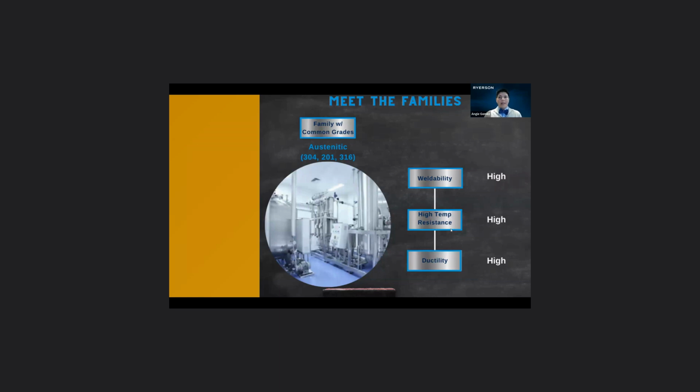If you see an L, for example, 304L on a test report or stenciled on any material you might have received, that means it has a low carbon content, composing less than 0.03 of its chemistry. You see austenitic metals used for food containers, tanks, silos. Most general purpose and cosmetic applications will use this.